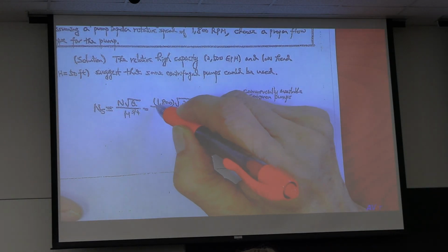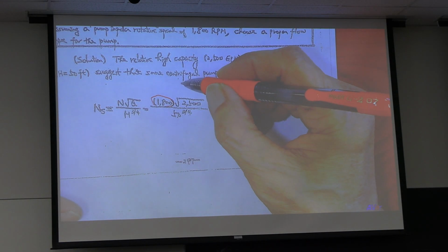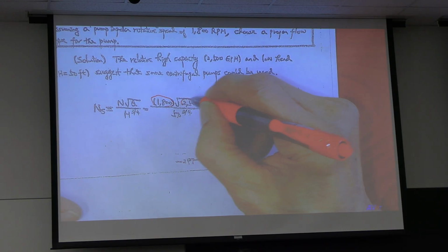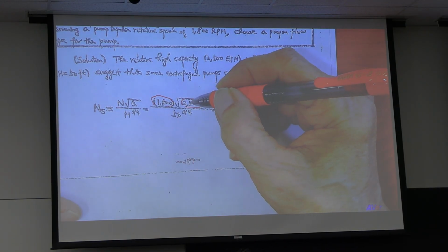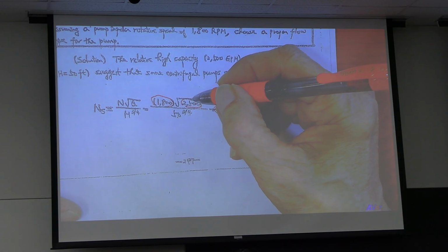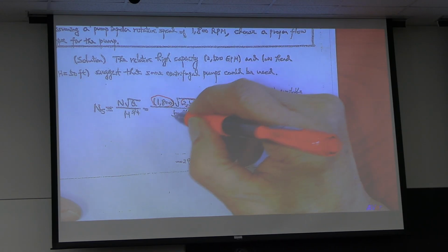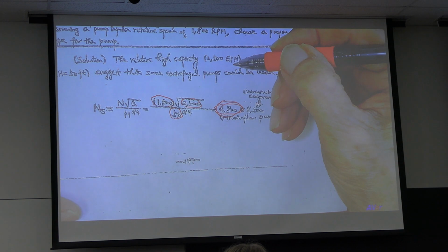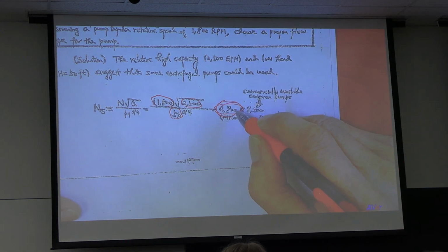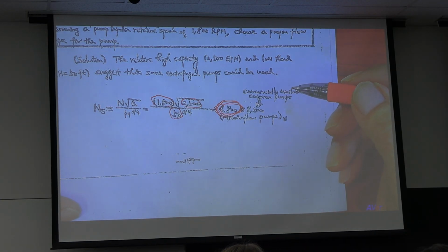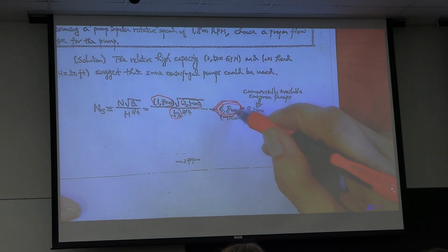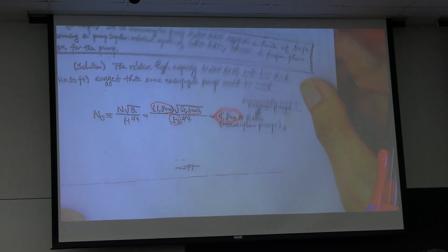Example, impeller speed 1800, pumping rate 2,500 gallons per minute, discharge pressure in terms of foot of liquid 50. Their specific speed is 4,800. You can buy this pump. That is the first thing we talk about, specific speed.